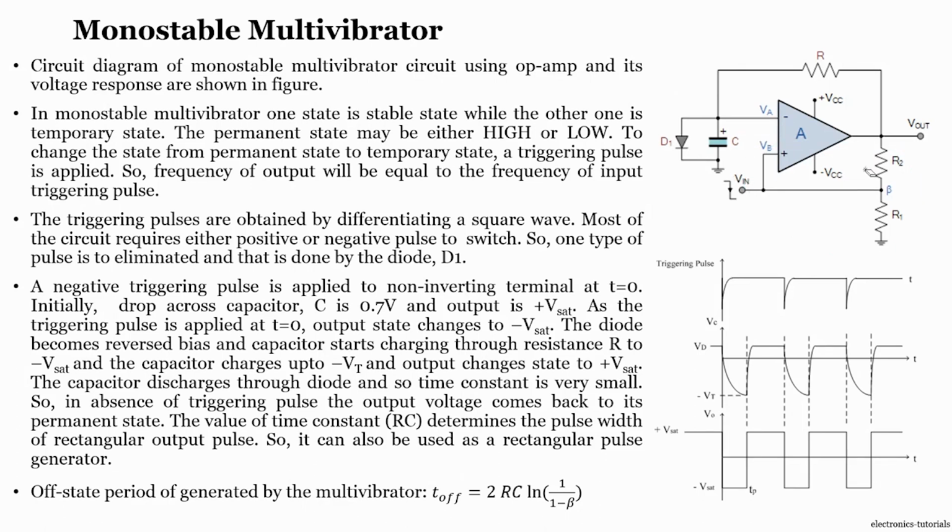That positive feedback means nothing but the resistors that we use in the positive feedback decide the value of beta, right. If we want to understand how exactly the circuit works, recall our previous astable multivibrator. We understood that because of the positive feedback, because it looks similar to our Schmitt trigger, it gives some thresholds, a positive threshold and a negative threshold. And since the output is connected to an RC filter, and the junction of RC is given to the negative input, when our input voltage is greater than the threshold, then either it goes to plus VCC or minus VCC based upon the input signal.